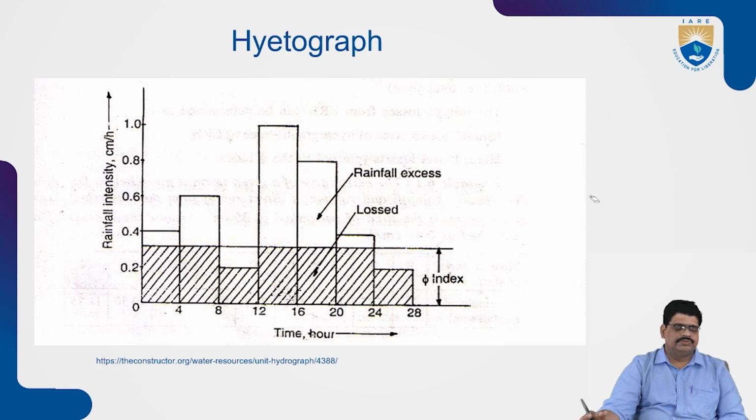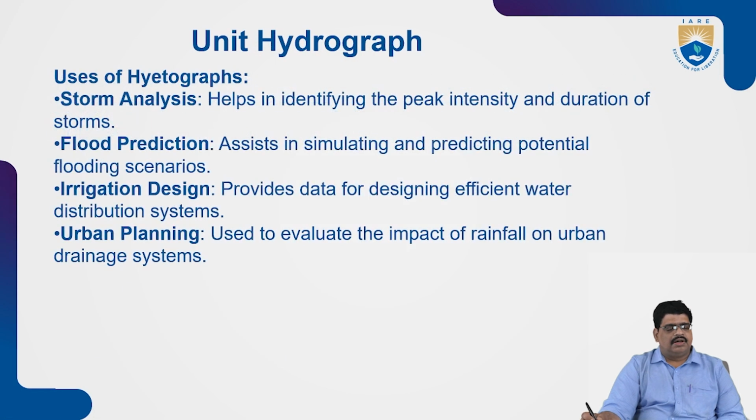Right. Next, storm units, uses of the hyetograph. What is meant by use of the hyetograph? A hyetograph is nothing but a storm analysis. The storm analysis can be represented here, which helps in identifying the peak intensity, and the duration of the storms will also be calculated.